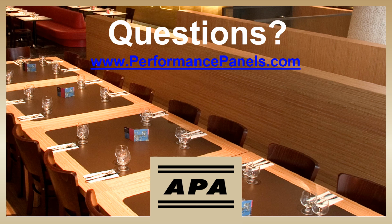Yeah, that's a good question, and it's certainly a hot topic of conversation. So your structural plywood, which would be specified to PS1, and for that matter, any wood structural panels that could be specified to PS2, they've all demonstrated such low levels of off-gassing that they're actually exempt. And this applies to products audited under APA's quality assurance program. And this does apply to products used in both industrial and construction applications.